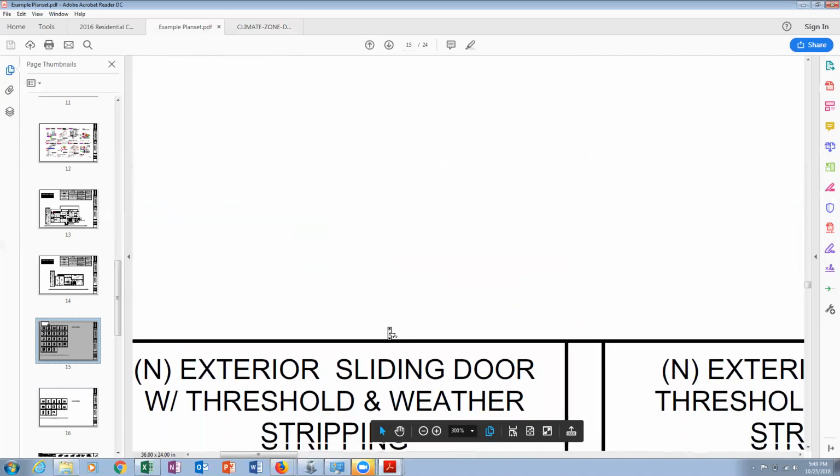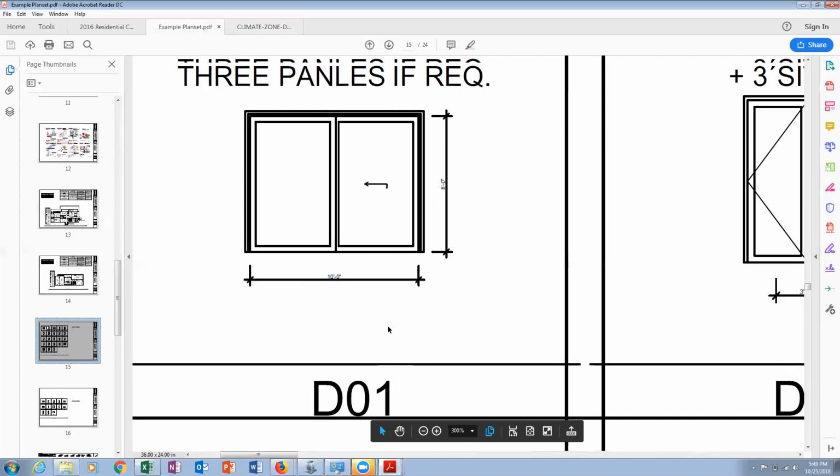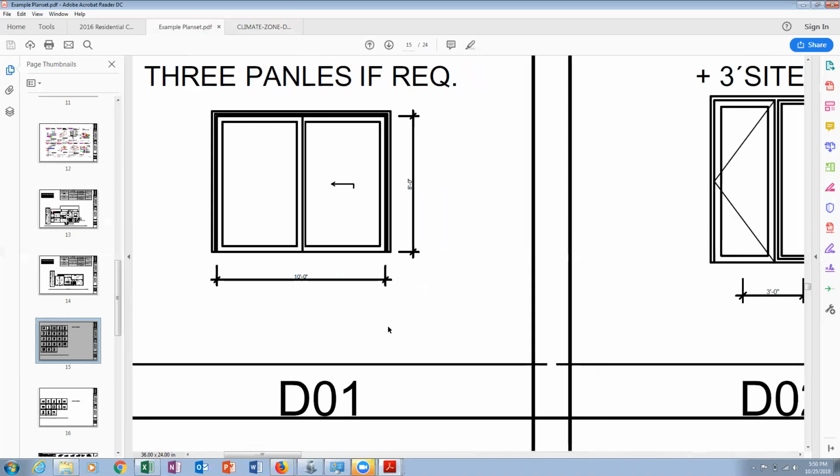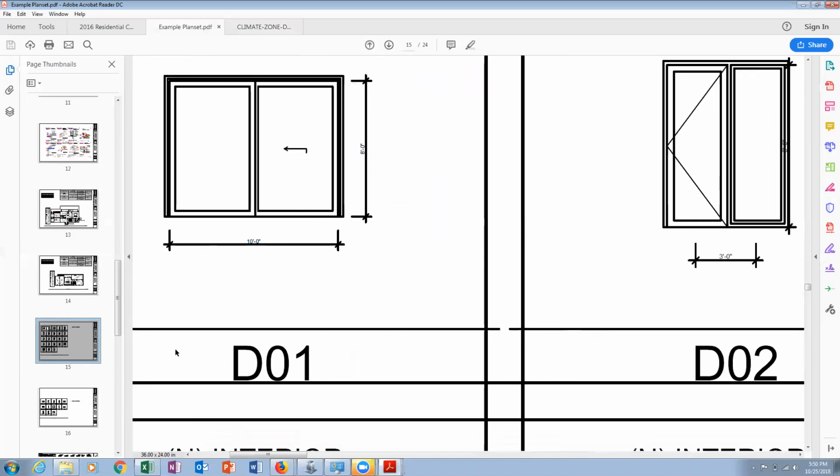And then they give each its own code. So this window, for example, is 10 feet wide. Okay, so that's probably a slider door. So 10 feet wide by 8 feet tall. And that's the way that we take the dimensions for windows. We do width first, and then height. So for example, with this window, if it's 10 feet wide and 8 feet tall, we would call that a 1080. So it's 10 for the width and then 80 for the height. And that's just your feet and inches. And that's how we'll break it down in the spreadsheet when we get to that point.